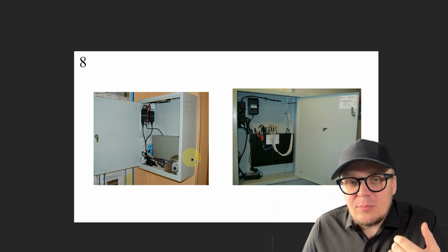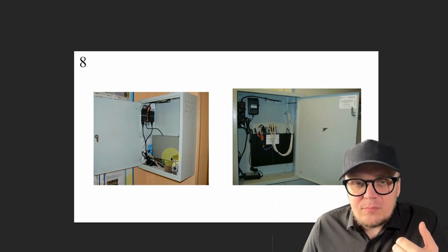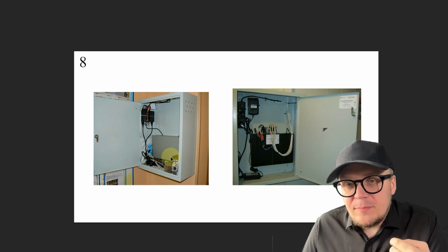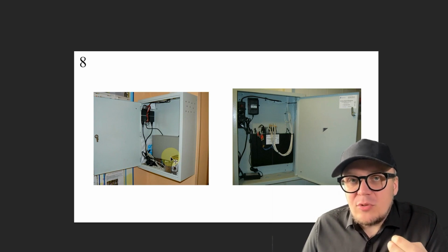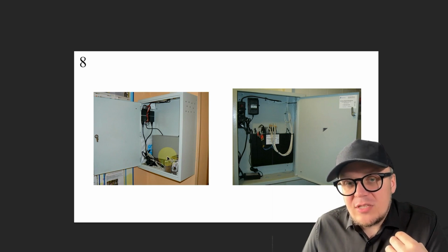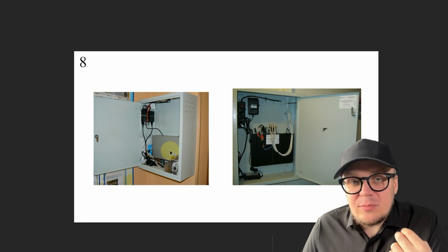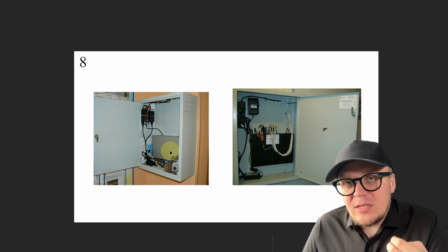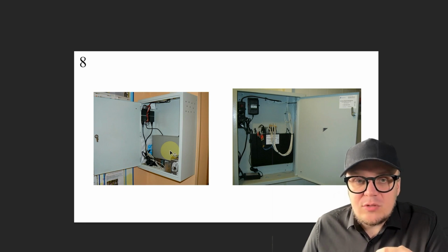The next common mistake is when you place the DVR in a poorly ventilated room. This often happens when people hide the DVR in cabinets, metal ones, in safes. The DVR should operate at a temperature from 0 to plus 55 degrees Celsius. Accordingly, if the temperature is higher, your recorder will overheat, the hard drive will constantly be running hot, and sooner or later, the DVR itself will burn out.